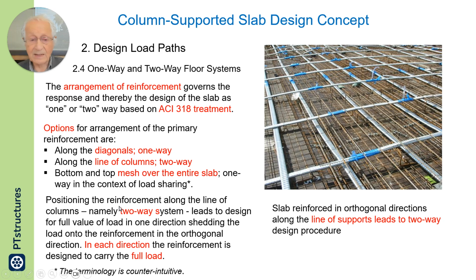Positioning the reinforcement along the line of columns, namely two-way system, leads to design for full value of load in one direction, shedding the load onto the reinforcement in the orthogonal direction. In each direction, the reinforcement is designed to carry the full load.